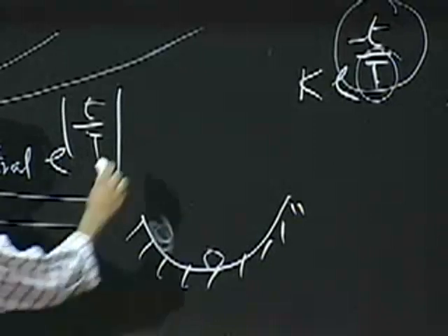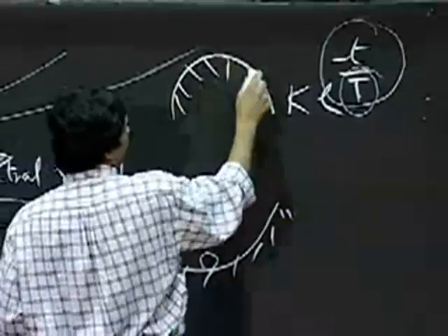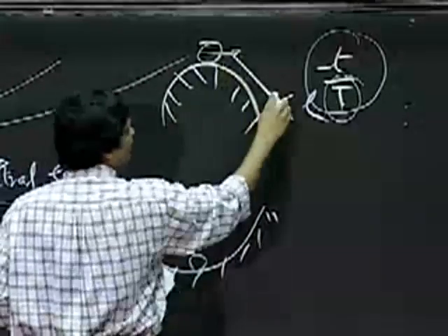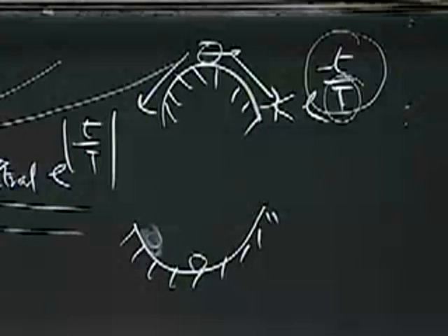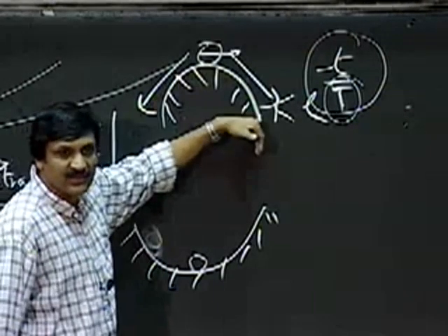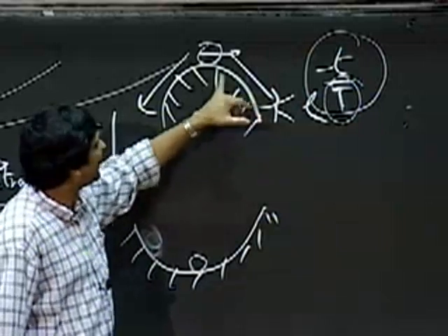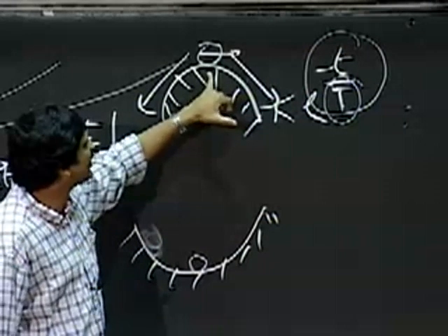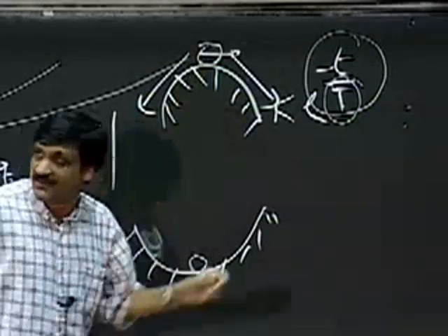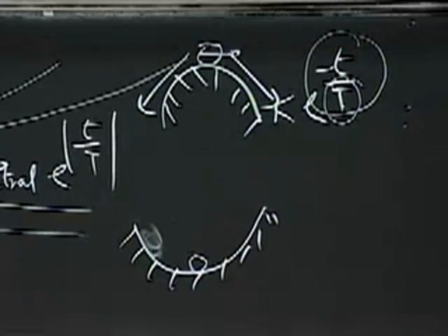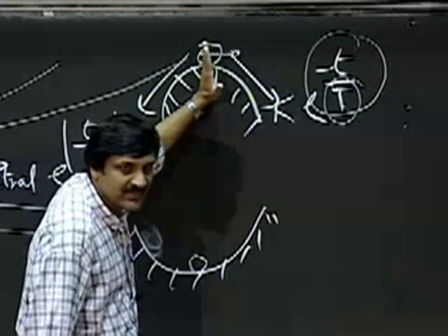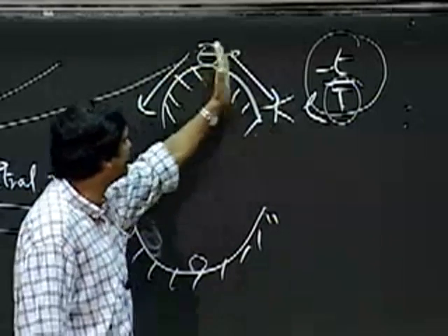Okay? The unstable situation is this situation where I have a ball sitting up here where any small perturbation will get it to zip down to a positive rail or to the negative rail. So this is an unstable equilibrium situation. And exactly the reason we got this analysis in the static situation is that this can happen. If I do this circuit here and don't perturb it, then I could get the output sitting at 0. But the slightest perturbation, boom, it's going to fall down or go up.